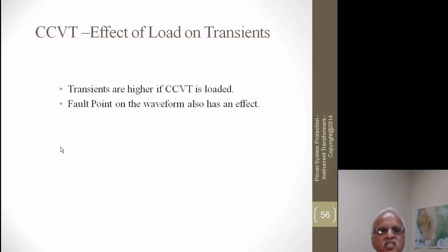The two key points we took out of that were that the CT never saturates at time t equals 0 plus, and that it comes out of saturation after some time. We make use of this in the operating principles of the relays to determine whether CT saturation has occurred or not. And then we went into voltage transformers.